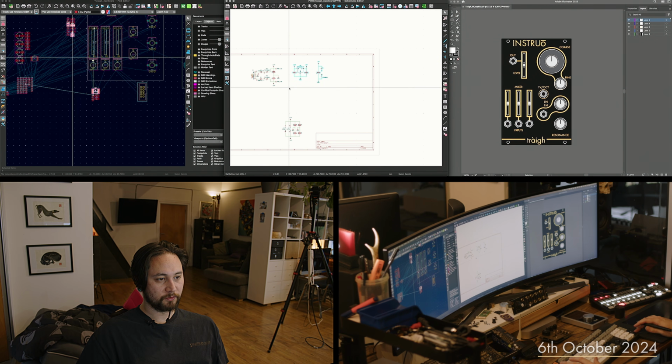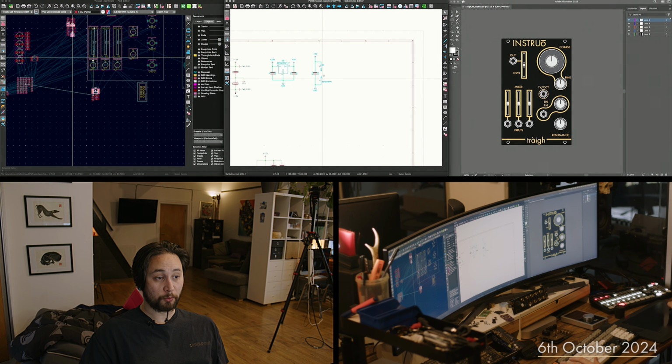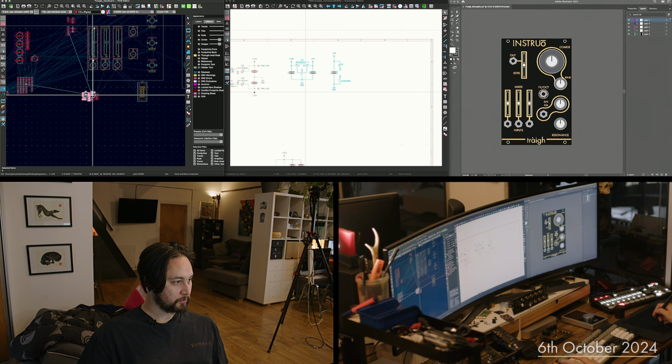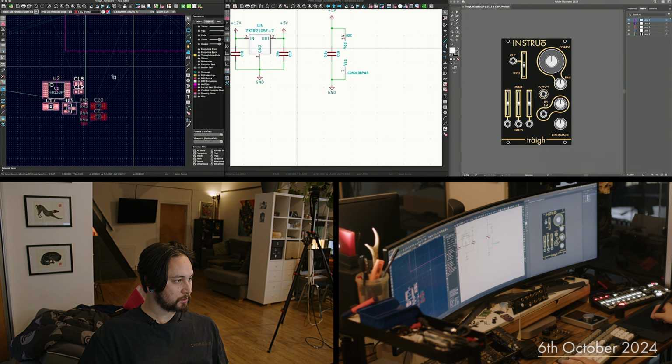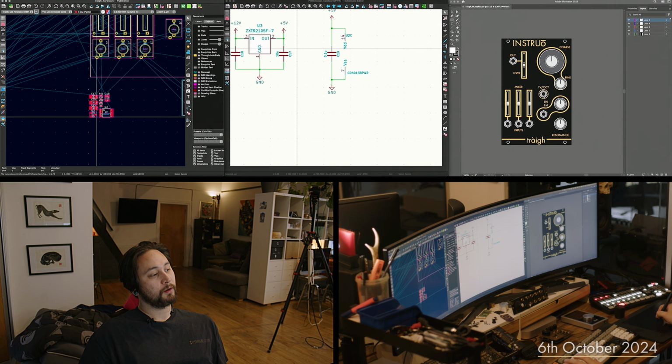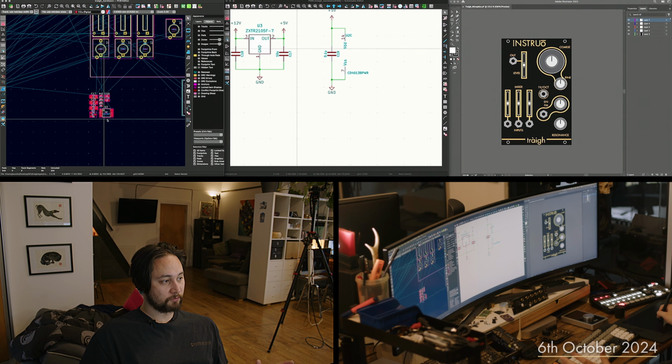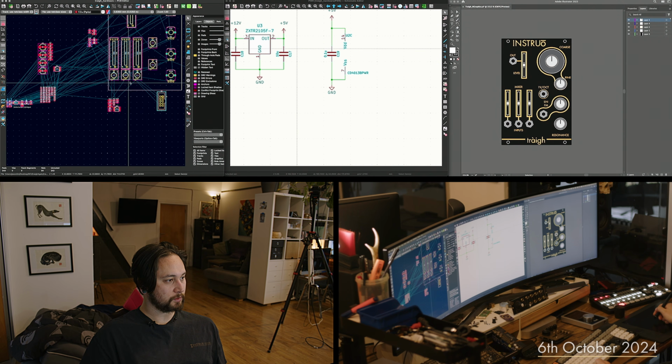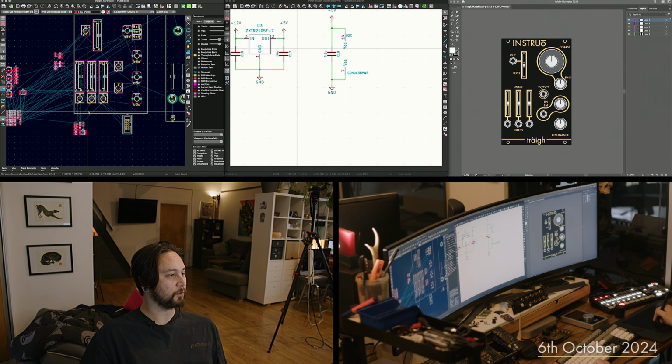That'll be all this stuff. That is the bypass capacitor for the power pins of the 4013. Let's pull them together as well. There's that, and here we go. So that's my entire 5-volt regulator and flip-flop divider circuit, and that will neatly fit in the bottom corner there.